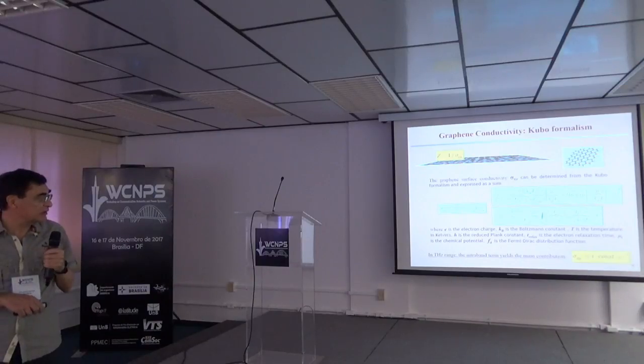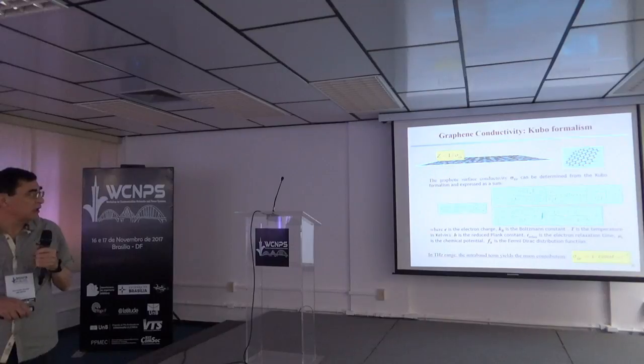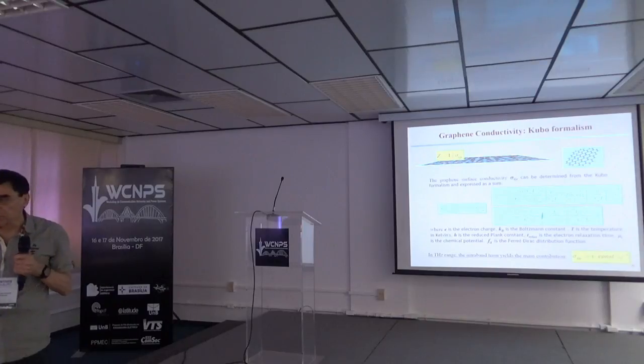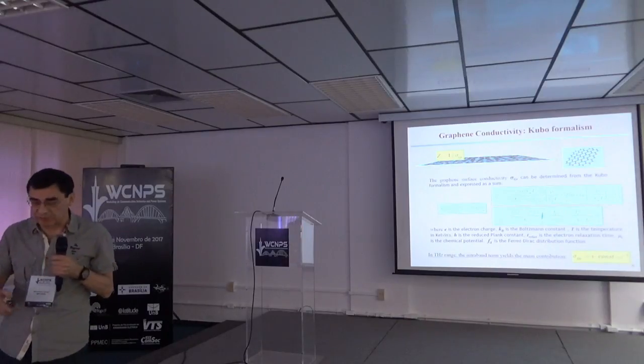The total conductivity is the sum of these terms, but in the microwave and terahertz wave range, the first term dominates. And you can see that the frequency is in the denominator. Therefore, the conductivity goes down with frequency, and impedance is going up with frequency.